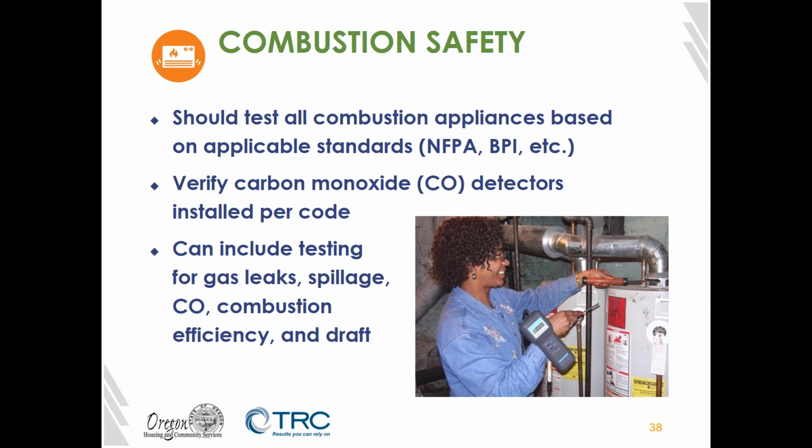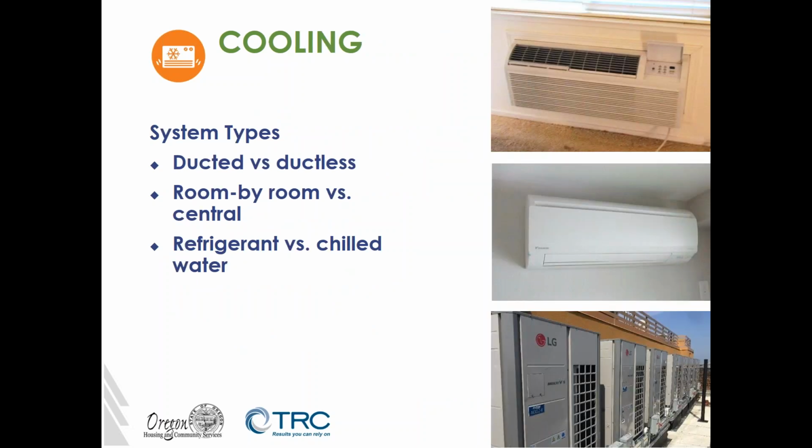We need to verify that carbon monoxide detectors are installed per code, and the type of testing you do on these can include things like testing for gas leaks, testing for spillage, carbon monoxide, combustion efficiency, and draft. And we will talk more about these in the health and safety webinar.